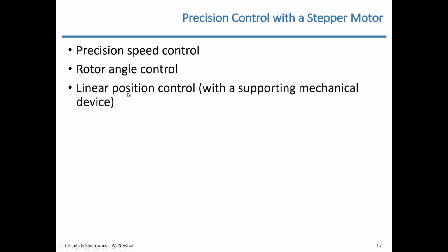And if you attach the rotor to a gear or to a pulley and then attach it to a chain or a belt, then you can control a linear position with a stepper motor.